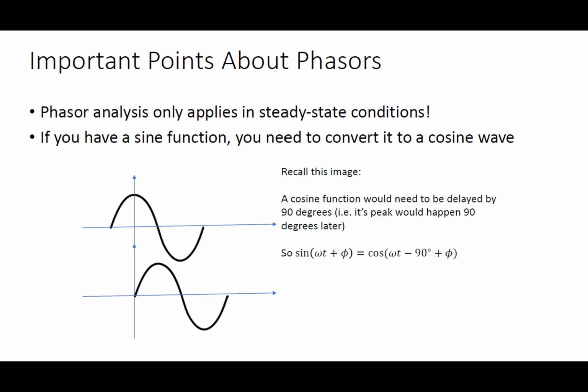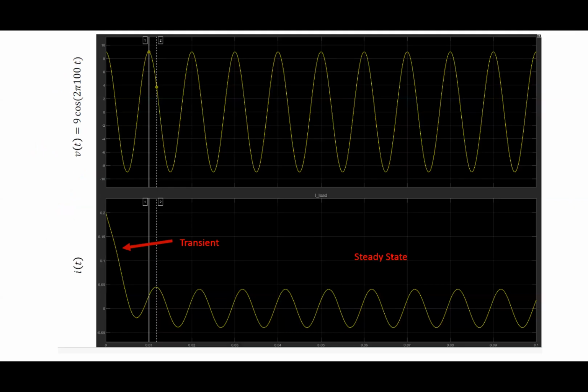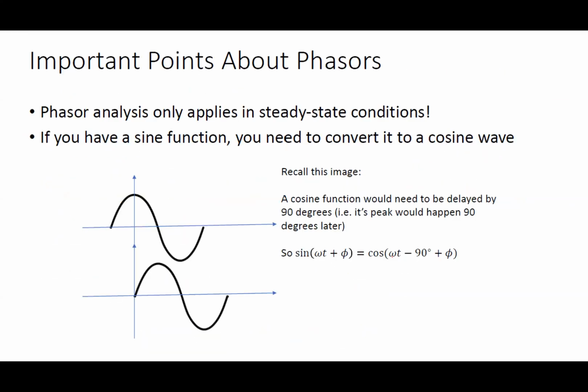Now, you were at my house yesterday, I lost power. A lot of you probably did too, because of the storms. There's a transient then. In the utility world, sometimes they'll call that cold load pickup, because the amps are actually higher for a little bit during startup, and you have to be able to deal with that problem potentially. Those are real problems that exist, but they happen on the day of a blackout. They don't happen 99.99% of the time, so we don't focus on them as much.